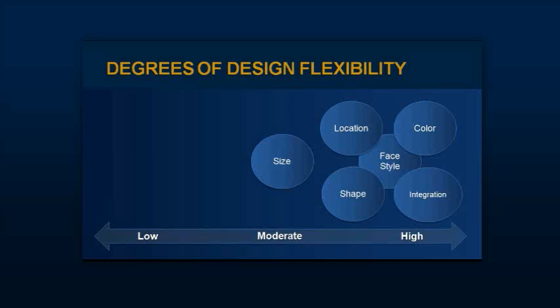And we typically, as a design rule, say you shouldn't be closer than 3 feet if you're going to be in continual occupancy to the face of that diffuser. But in reality, you can be within 2 inches of it, still not feel the face velocity coming out of that system because we designed for 40 feet per minute. Now, because we're not mixing the space, this allows the cool air to pool on the floor.